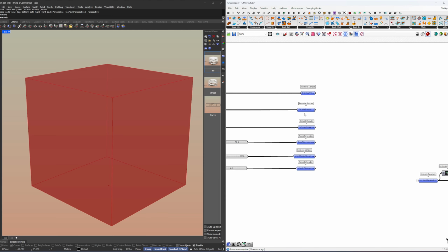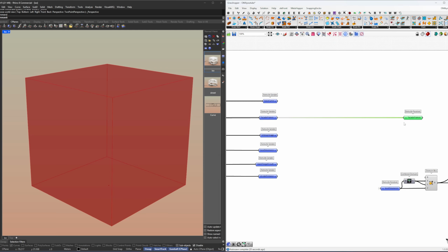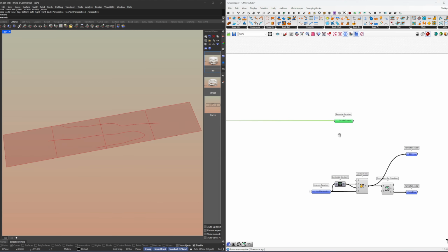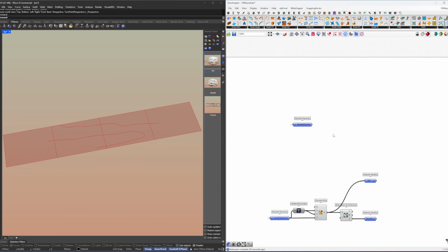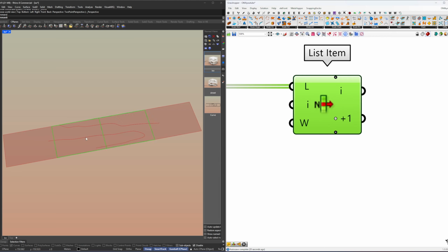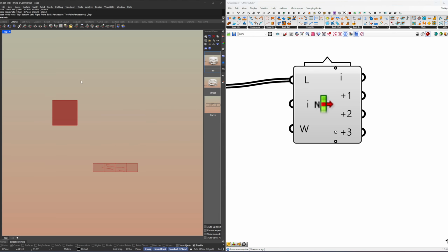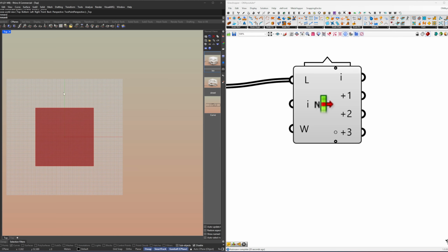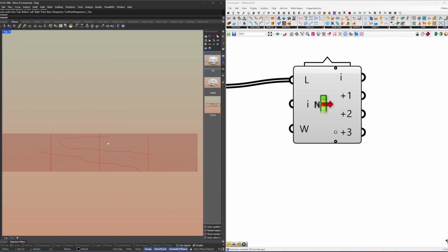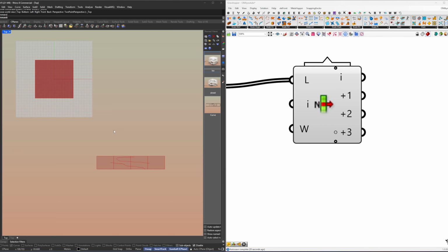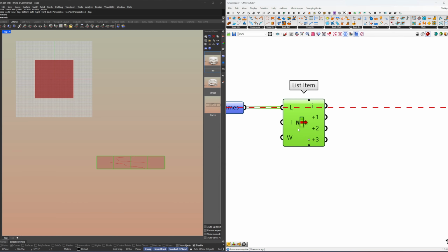The second part is that we need to bring the facade frames, because it can be that they are not sorted in the right way. So what I mean, this one, this is exactly what I mean. Right, so this is 1, this is 2, this is 3, and this is 4. No, that can also make sense, but I wanted to just start over here. And since we're working, let's say this is the plane that we have, so green is the Y and red is the X. So we're just gonna use it once. So we're gonna sort these panels in the X direction.